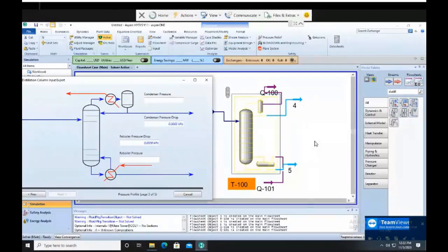There must be a pressure change from high pressure to low pressure. So, and also in here, it produces vapor. Okay, when it produces vapor, you want the vapor to travel upward. So that means that the pressure at your reboiler must be higher than the pressure of your condenser. But you want the component to flow inside the distillation column.